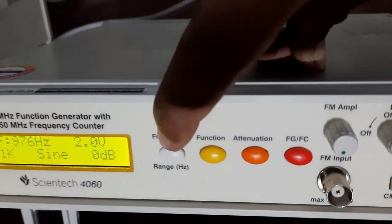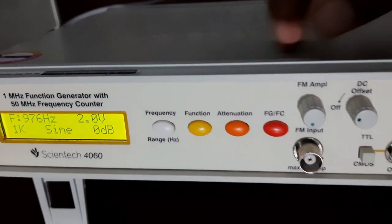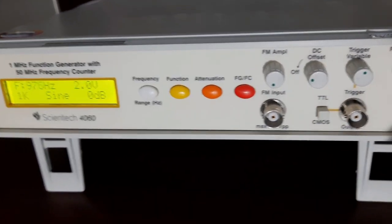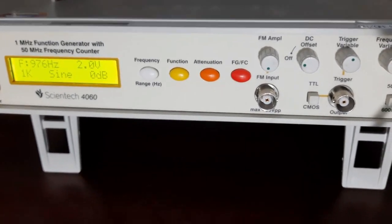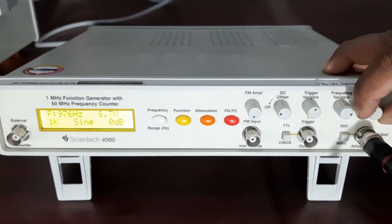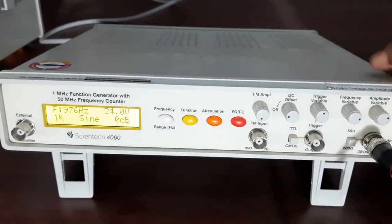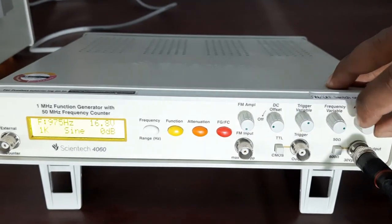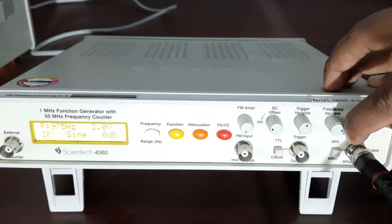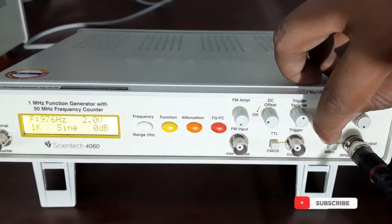And you can see in this we have so many types of buttons like frequency, function, attenuation. We can use these buttons in order to change the parameter of the wave. Now you can see, if I increase the value of amplitude variable, the voltage on the screen is increasing, like that 23, it is now 24.04, it is the maximum value. Now if I decrease again, the amplitude on the screen will get decreased. Ultimately we are changing the amplitude of that wave which is coming out of the function generator.